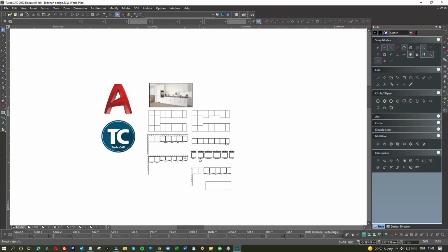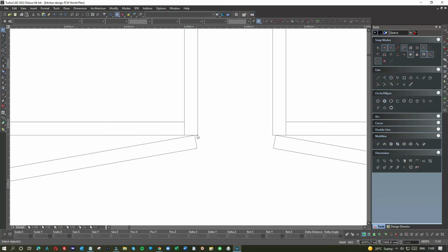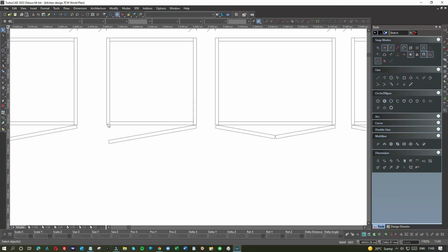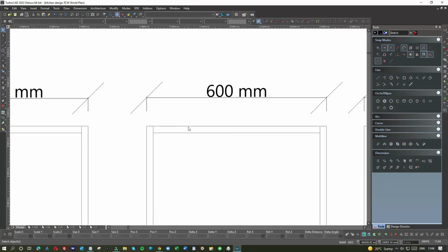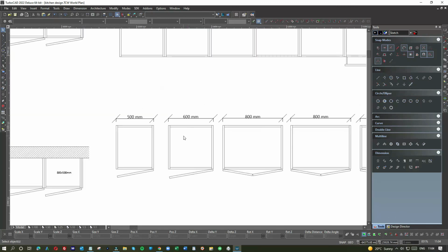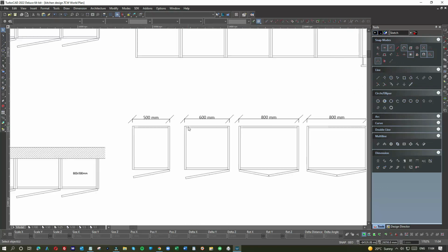I've told you about the doors. Easy little trick to make sure your door doesn't hang from the edge. It needs to hang from 5 mil in, and doors are always about 10 mil less than the actual carcass to facilitate opening and closing. Carcasses are 22, and the side panels go the whole way in, and then these strips here are just joining panels. So when you're measuring it all out, it's important to know how these units fit together, and that's how they fit together.